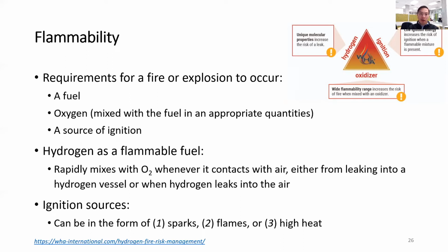Right. So when it comes to hydrogen, hydrogen obviously is a flammable fuel, because with its high diffusivity and high buoyancy, it would rapidly mix with oxygen whenever it comes into contact with air. Such contact can come from either hydrogen leaking out of the vessel into the air, or air actually leaking into the hydrogen vessel. So you need to be aware of this. And the ignition source normally comes in the form of spark, flame, or high heat.